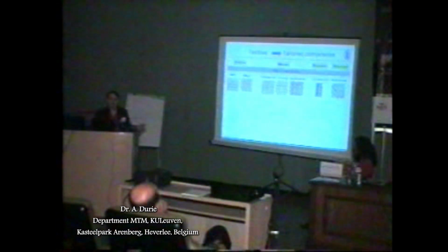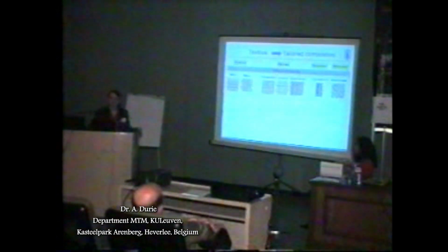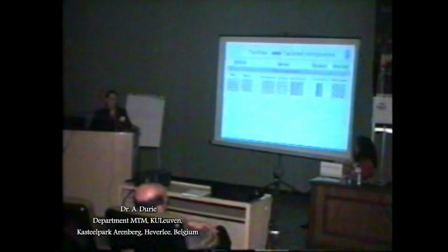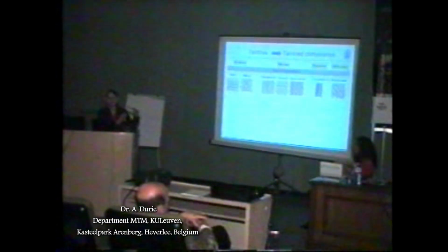There has been some movement towards making more isotropic materials in weaving. So for example, triaxial weaves and the development in quartaxial weaving in Italy are interesting examples of multi-axial weaving where we're aiming for more isotropic properties. The same with braided, we've got a whole huge range of materials that are possible. All of these 2D materials, or 2D because they're single layer, are usually made up into a composite material by laminating a whole range of the materials together.